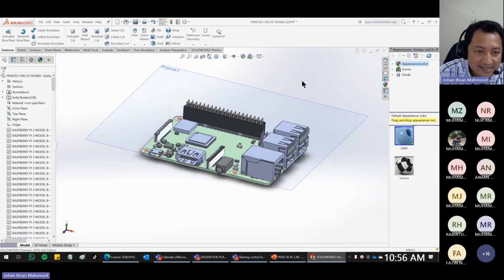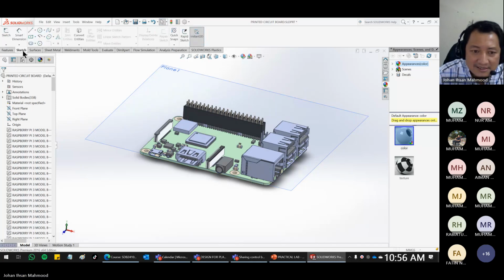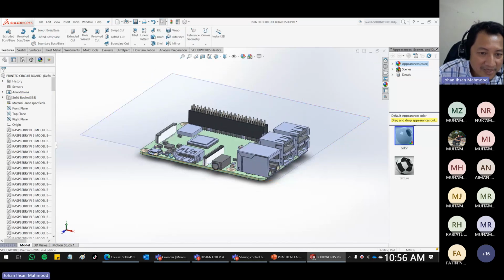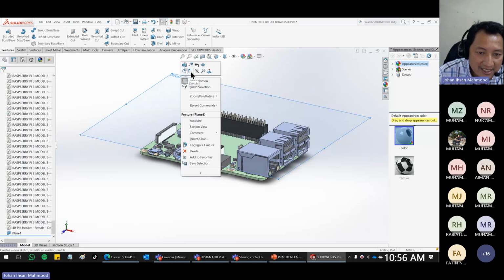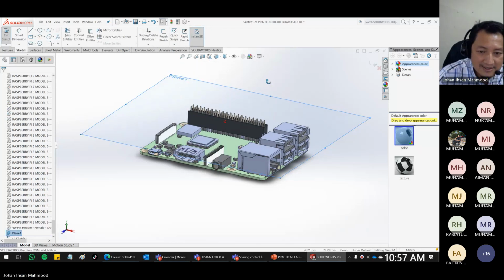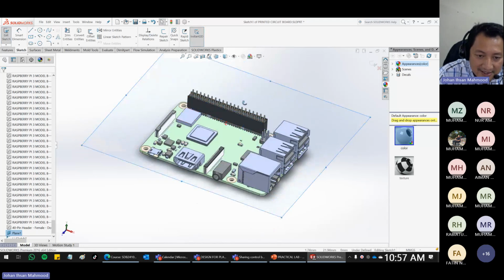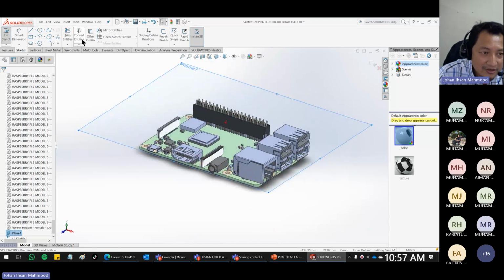So what I do is I choose something called sketch lah. Am I sketching now? Tekan button sketch. Baru jadi. Ataupun kamu kena pilih balik plane ni and then right click tekan sketch. Boleh je lah. So now I want to copy the features at the bottom right. So cara dia mudah je lah. Saya tekan ni, convert entities.